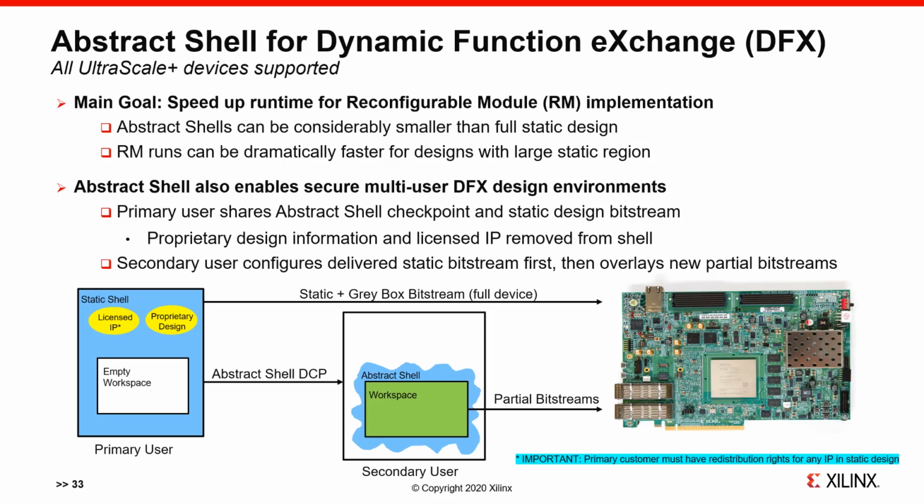For a DFX design in UltraScale Plus, after the parent implementation is complete, you can create an abstract shell for each reconfigurable partition. The main advantages of abstract shell include runtime reduction for reconfigurable module implementation, and it also enables secure multi-user DFX design environments.